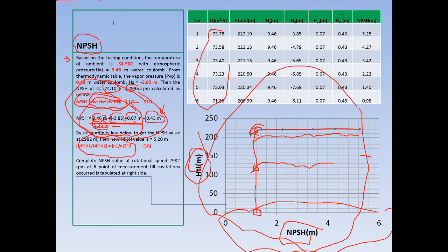Of course there are losses there, flow losses. The higher the flow, you calculate using the Moody chart at the piping how much the losses are, etc. But just to simplify, you just put it. So now it's very easy already. You test NPSH required, and then you compare with NPSH available.